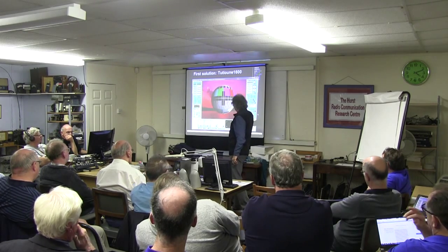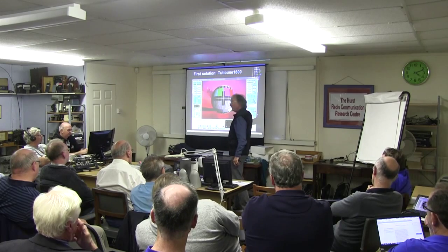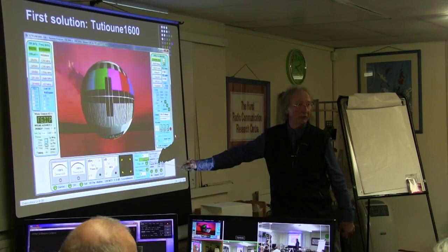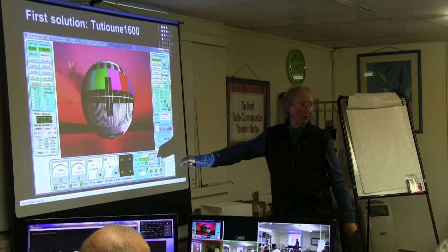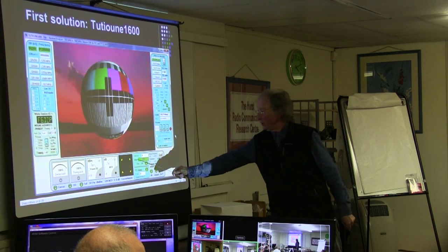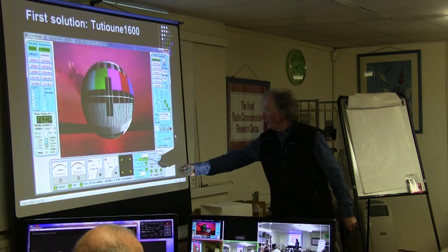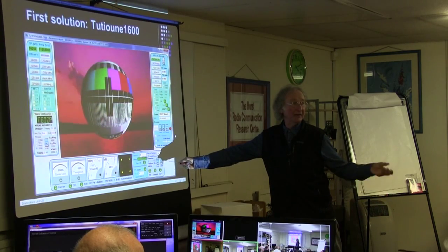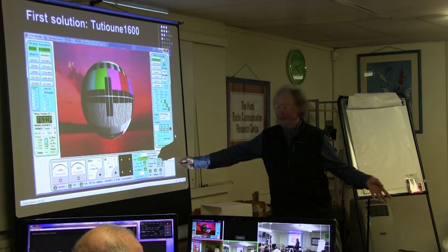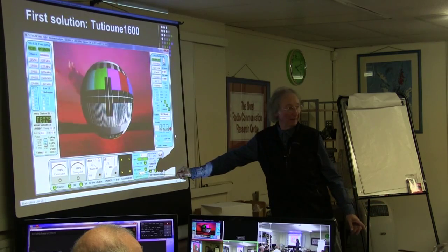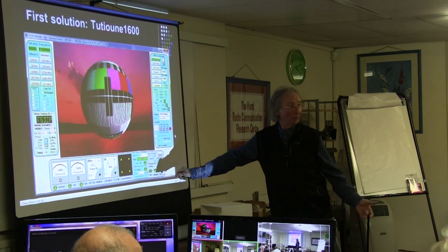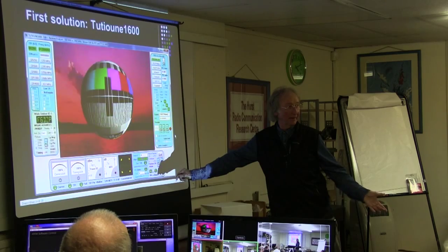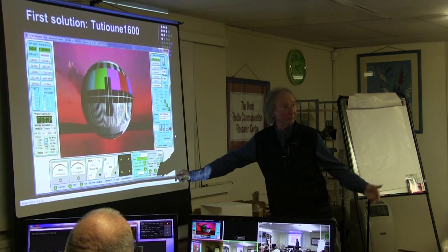We have also the work made by the Viterbi decoder. You can know the number of errors you have. It will go more and more up when we have difficulties, and at one time it cannot correct all the packets, and you will see here some number of packets that have not been decoded.